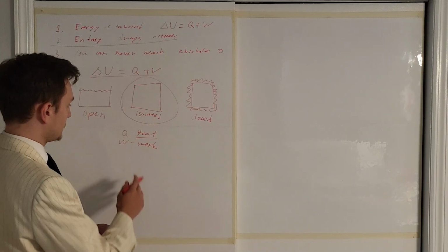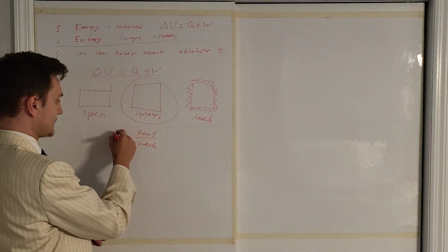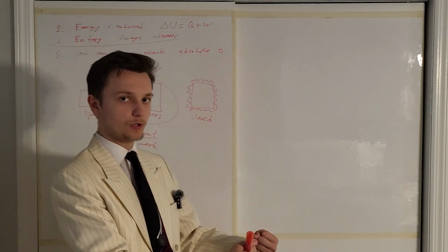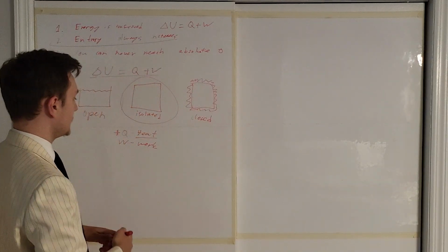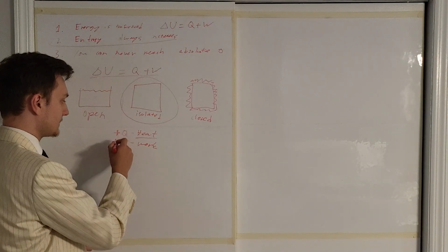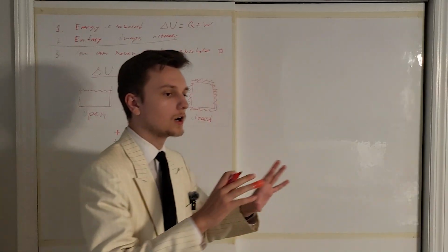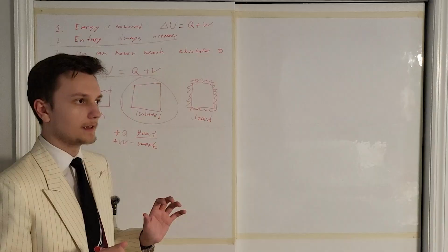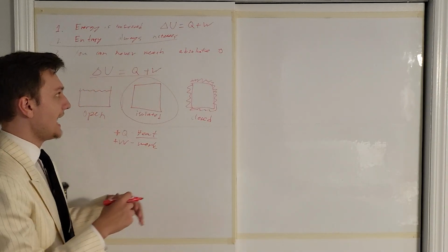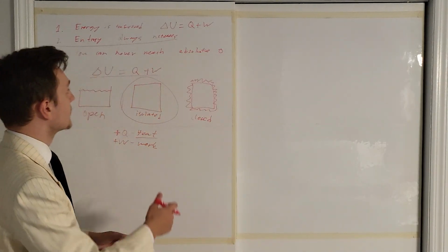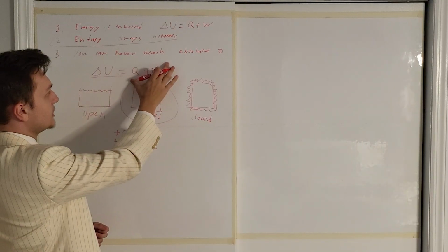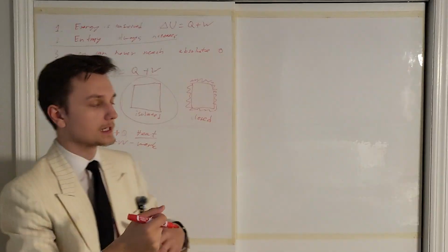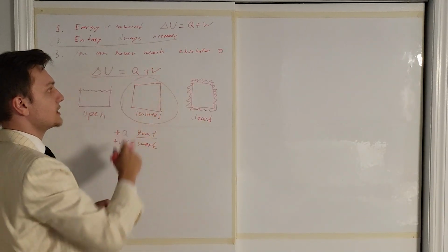By this definition, if Q is positive, it means you are adding heat to your system. If work is positive, it means you are doing work on the system. Think about it this way. If you are adding energy to your system, that needs to show up in this equation as a positive number. If you are taking energy away from your system, that needs to show up in this equation as a negative number.